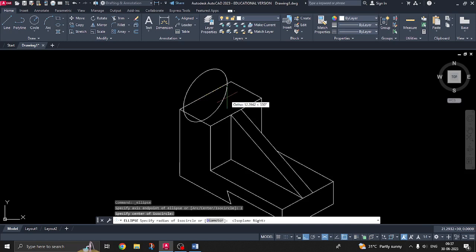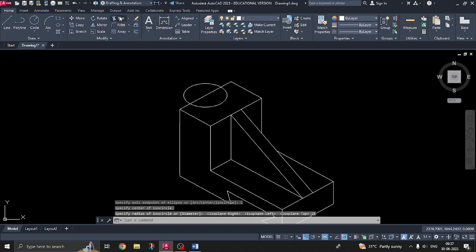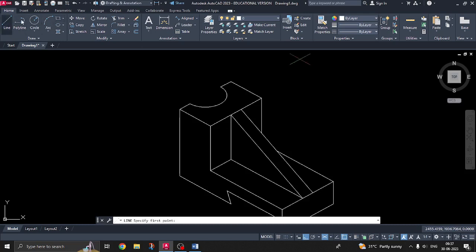If it is like this, you can change the isoplane. Okay, F5. Now if a suitable surface comes, you stop, and then you type the radius of the circle, as we know, 15. It is done. Trim. Okay, one more thing, that line should be a vertical line, that edge should be visible downward. Isoplane F5, you draw a line until it cuts the ellipse and trim unwanted. Okay,